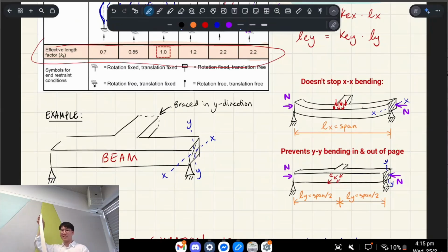But basically in structures, you're gonna find that sometimes another member that's bracing it is only gonna brace it in one direction. So for example, if my hand is bracing it this way and it locks it in, and it can't go like this way. Say my elbow is fully rigid, but for whatever reason it can go left or right. That's when it's braced in one direction and not the other. So you kind of have to think about that, if that makes sense.